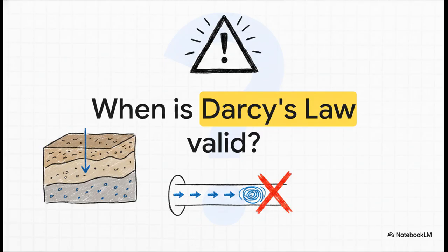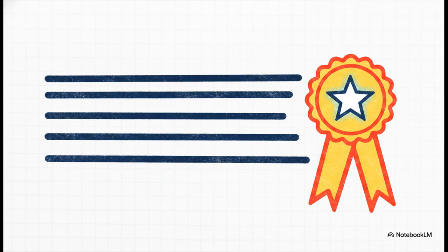All right, question 2, hitting on the math rules of seepage. Think back to that one strict condition we mentioned. For which specific type of flow is Darcy's Law actually valid? Laminar flow. Awesome job if you got that right. They love to try and trick you by throwing turbulent flow or transitional flow into the multiple choice options, but don't fall for it, it's gotta be laminar.